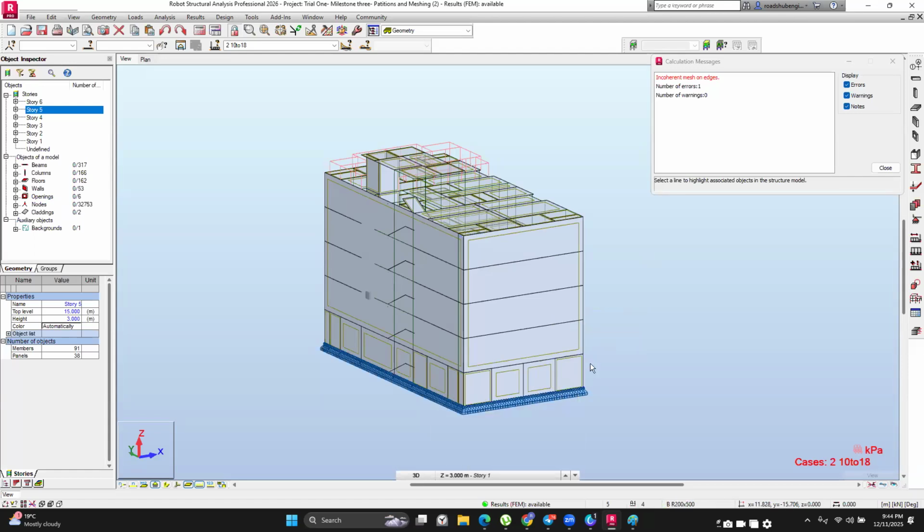Hello, engineer. Sorry, Alan, let me just weigh in on that. There's something called a wind tunnel simulation. If you are doing very tall structures, or you are in an environment that extreme, you would have to do a wind tunnel simulation. They are rather expensive because you need specialized personnel to do that.